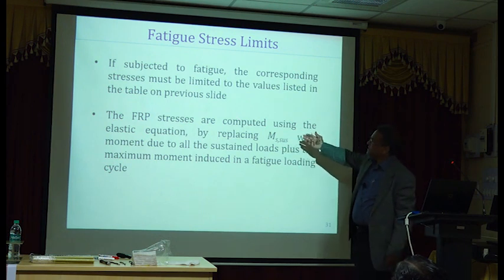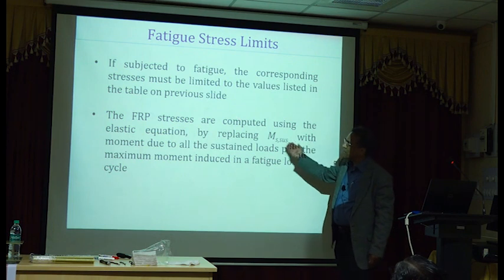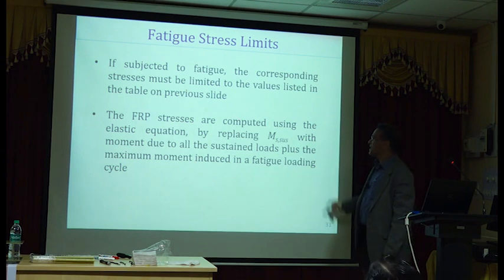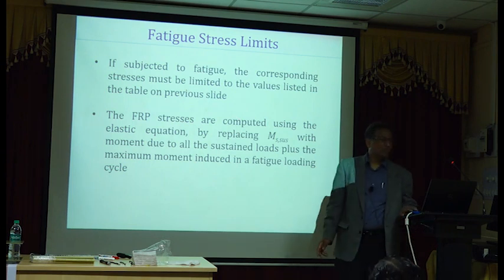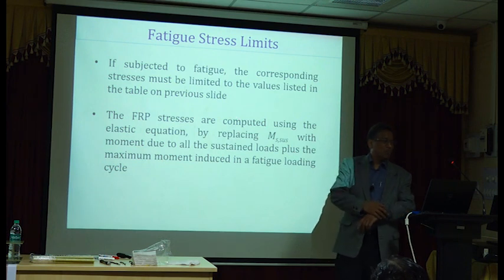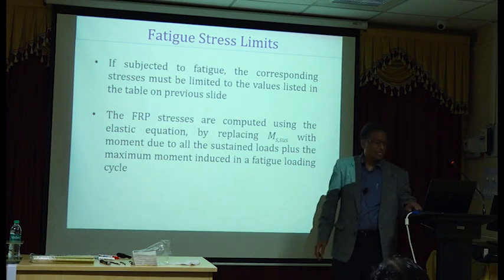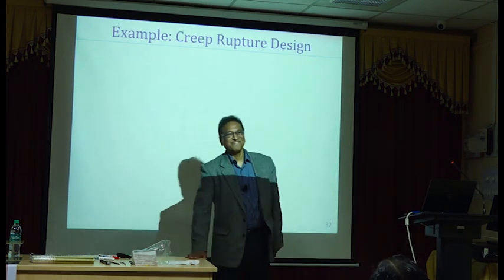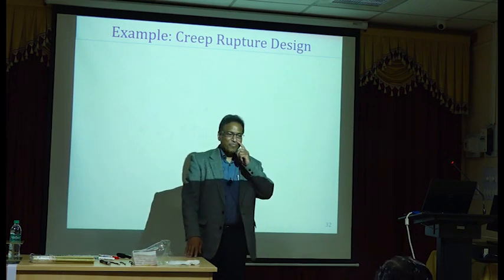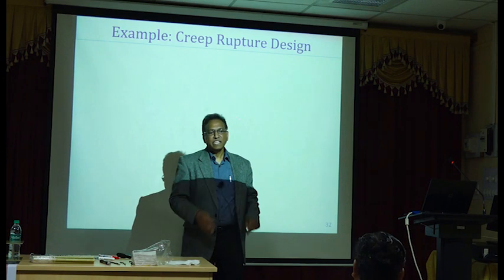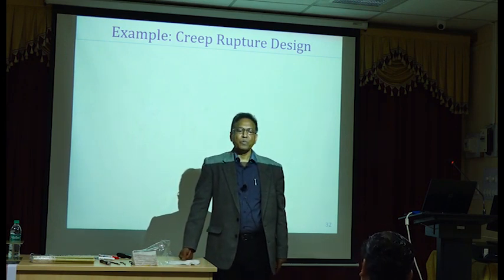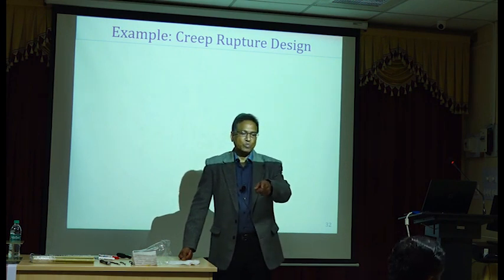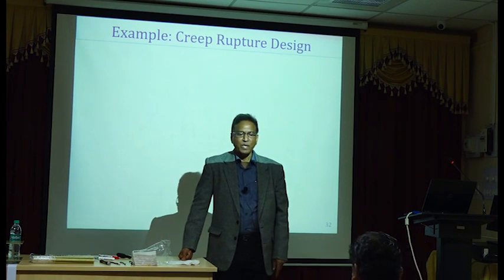Once again, we will calculate our stresses by replacing M sub s sustained with the moment due to all the sustained loads plus the maximum moment due to the fatigue loading cycle. Okay, that's what we will need to use. So the good news is that's the last slide for today. But the bad news is you get a quiz. And of course, we also have an example. I initially thought I would go over that, but it's already 1:30, so we will end the session for now. But Dr. Das was very kind to print the example for you.